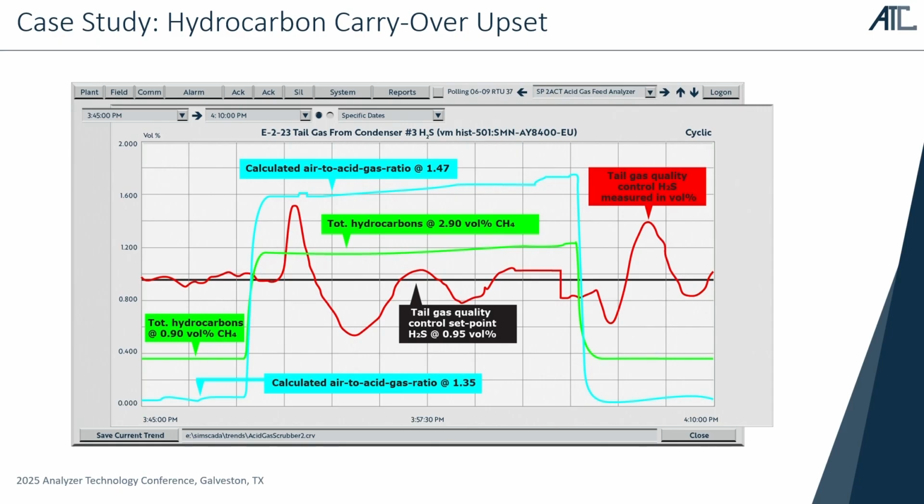We move to the right a little bit, and basically what you see is that after about 10-12 minutes, hydrocarbons were removed from the system again. The injection basically was stopped. So this reflects not a 10% upswing in air demand, but a 10% reduction, again evidenced by the air demand change in the blue line. And you see basically the same result of the system response reflected by the red line.